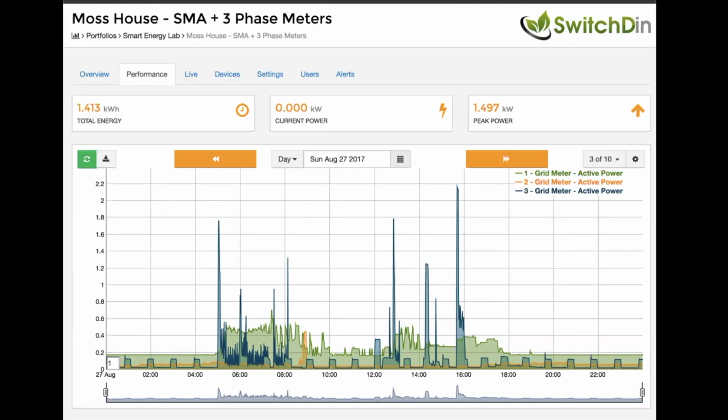dishwasher coming on. It's a heating element. And you'll see it drops down at about 1600 hours. That's because it's heated the water and now it's just swishing it around. But there are also, on the other two phases, some loads as well, so I need to add those in there. So I'm probably going to get up to close to 2.5, 2.6 kilowatts of demand of coincidental load. So this is a useful design feature, to be able to measure stuff before you actually build it. It's a bit of a luxury if the system hasn't got any appliances yet and someone's just telling you what they're going to get. But if you have the opportunity to measure, you can get a lot of information about their loads.